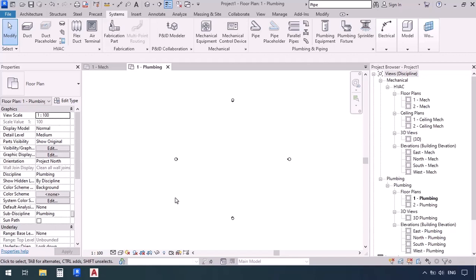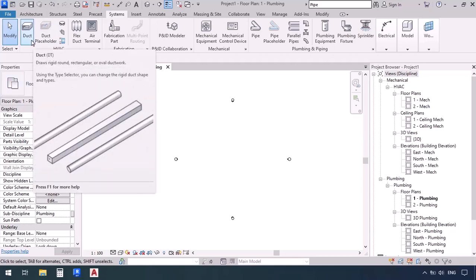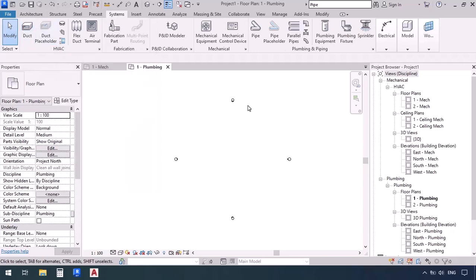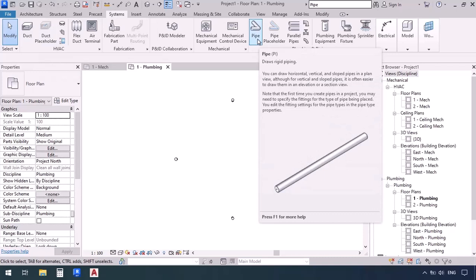Now, another good feature that Revit has is the tooltips. If I move my cursor onto each tool, a box will show up including some further explanations related to that tool. After a while, this box may expand more and give us some further explanations using images or videos about that tool. Actually, here's an example. I'm going to move the cursor onto pipe, and after about half a second, the box will expand, showing us more information. I can also see the image of the pipe.